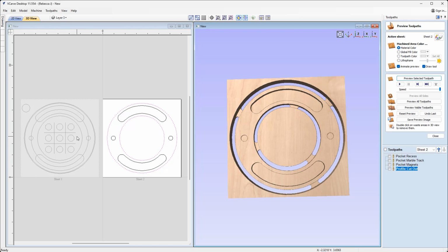So some things for you to take away. Obviously, whatever material you're going to be using, you need to alter the vectors according to the sizes that you're using, and alter the cut depths according to the material thicknesses that you are using. So you just want to make sure that the ring fits nicely flush with the cut depth that you assign for the base shape, okay? And so measure everything twice and hopefully cut once. So at this stage, let's go ahead and save out our toolpaths, and we'll go over to the lab and start machining those.